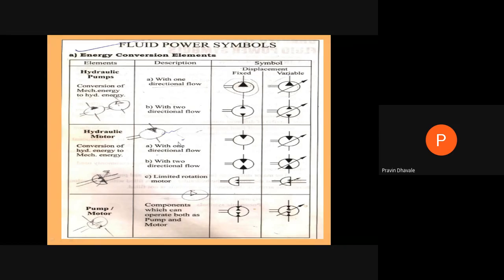Hydraulic pump, how will it be denoted? As far as a pump is concerned, the arrow pointer is touching the circumference of the circle. As far as a motor is concerned, the pointer is toward the center of the circle, and its base is touching the circumference of the circle. Right? This is one directional. This is two directional, and this arrow will show